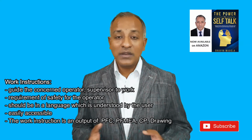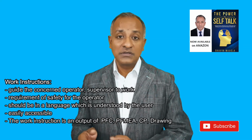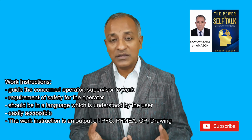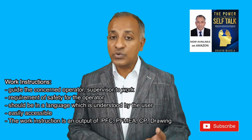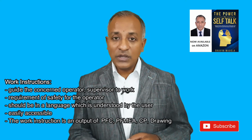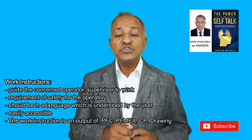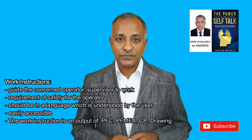Once these documents are ready, it's very easy to make the next document, that is the work instruction. Now, a work instruction is a document to help the operator and the supervisor do their work at their place. What are the inputs which make the work instructions? It can be the control plan, PFMEA, customer requirements, specifications, drawings. All these things become good inputs for the work instructions. It's very important to ensure that work instructions are in a language in which the operator can read, and easily accessible to the person so that they can refer to them as and when they want.